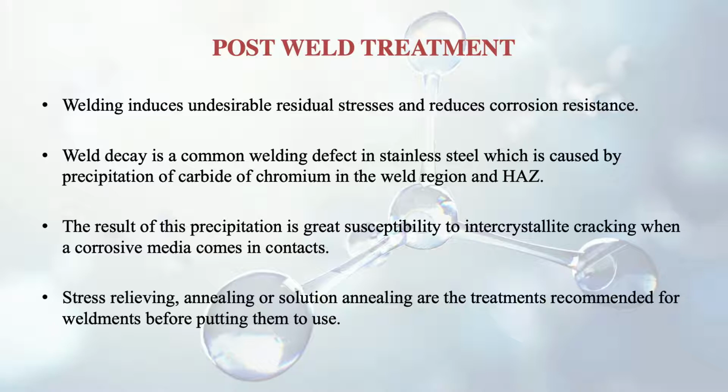Stress relieving, annealing or solution annealing, the three processes which we discussed earlier, are the treatments recommended for weldments before putting them to use. So we need these kinds of process before the weld can be said to be accurate or fine.